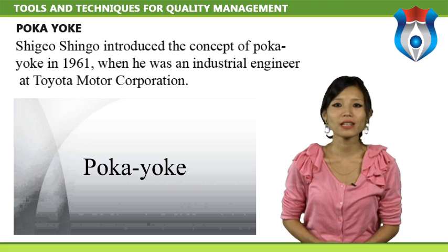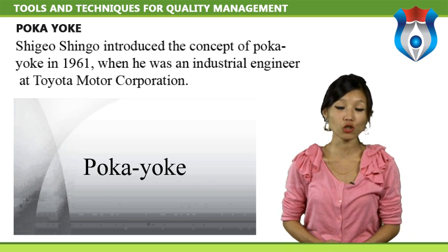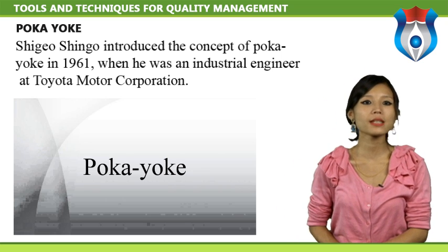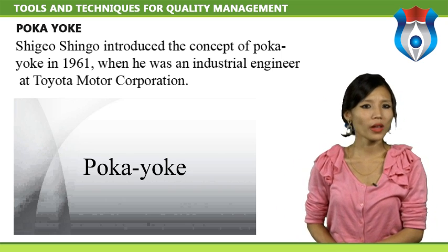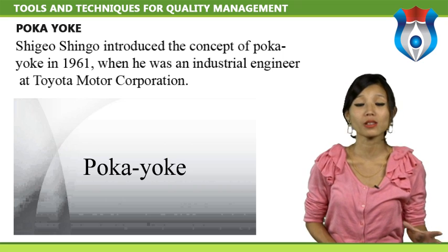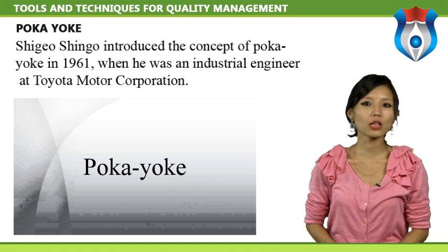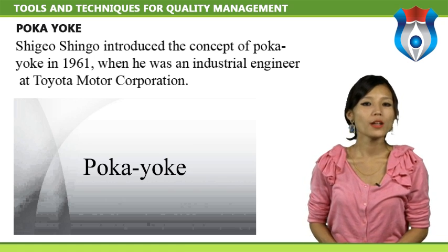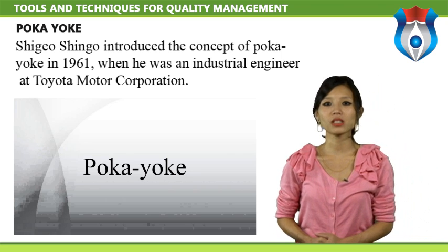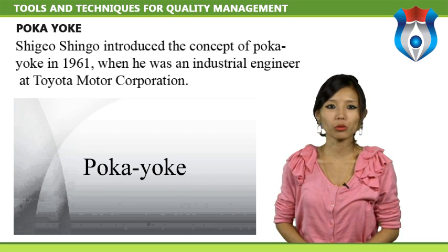Poka yokes are mechanisms used to mistake-proof an entire process. Ideally, poka yokes ensure that proper conditions exist before actually executing a process step, preventing defects from occurring in the first place. Where this is not possible, poka yokes perform a detective function, eliminating defects in the process as early as possible. The Center for Excellence in Operations (CEO) has developed a poka yoke framework to help its clients understand the various classification and application of mistake-proofing mechanisms. A brief overview of the framework is as follows.